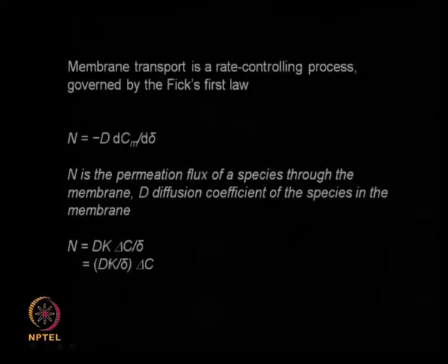So if you look under the property of the membrane, you will see terms like diffusion coefficient, that is diffusion coefficient of the species through the membrane, which is a function of the species as well as the membrane. Delta is like the thickness of the membrane and K is the partition coefficient, that means ratio of the concentration that is just dissolved in the upstream vis-a-vis the concentration in the feed. So these are the properties of the membrane and this is the driving force, that is the flux. Okay.